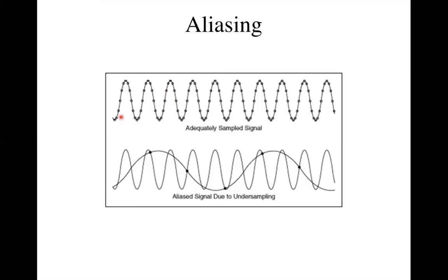A visual way to look at that is if I have a sinusoid of this frequency, say this is x space in millimeters, and I sample that oscillating function as a function of position. Obviously, this top one is well sampled. I can see the phase and the amplitude of the sinusoid quite well. If I drop that sampling by a factor of 20 or so, such that I get these samples, the function that I'm looking at now is a much lower frequency sinusoid.